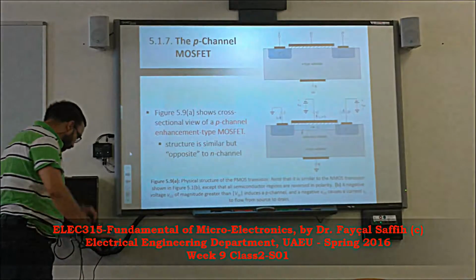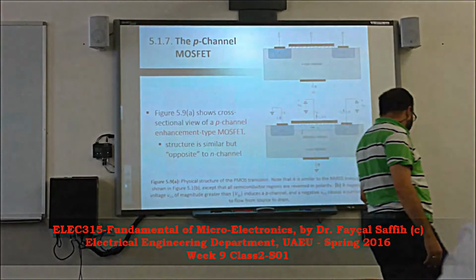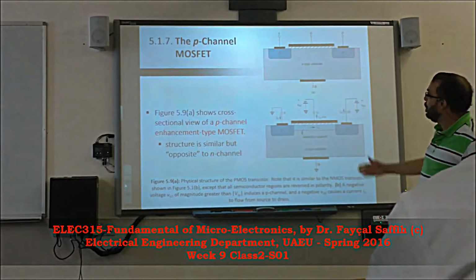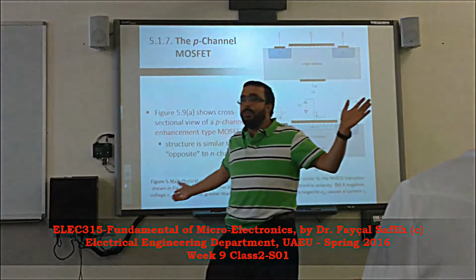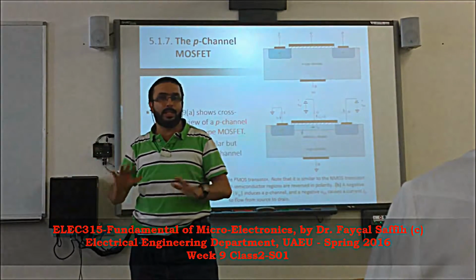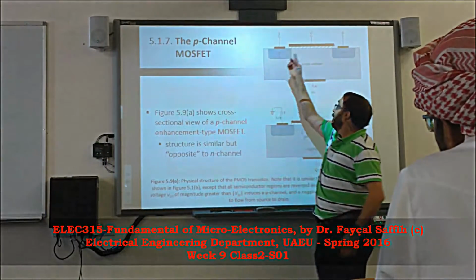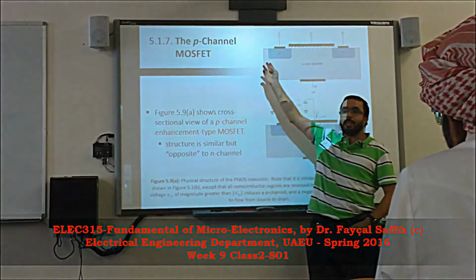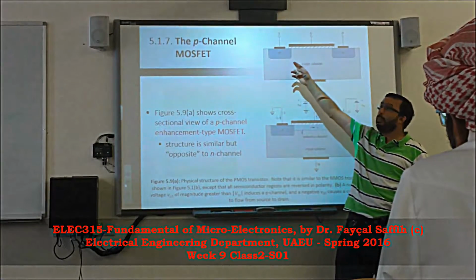Alright. So today, inshallah, we keep going on discovering more about microelectronics. We introduce the second device, which is the PMOS transistor. Here, as we did in the diode, basically we flip everything. What's N becomes P, what's P becomes N, and bingo. The rest stays the same. So the source and drain diffusion or implantation now becomes P plus. Heavily doped with donors or acceptors?